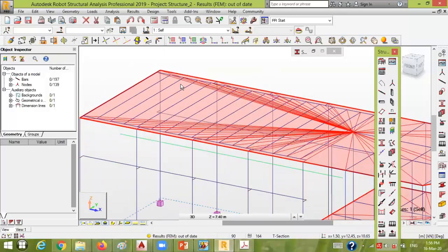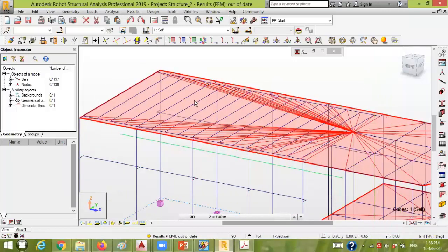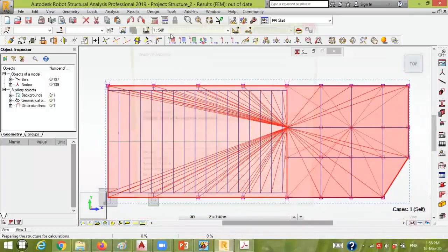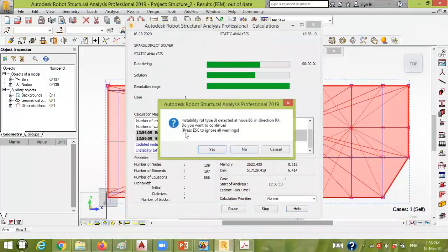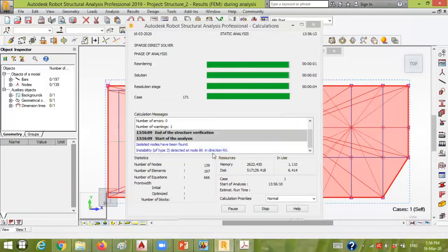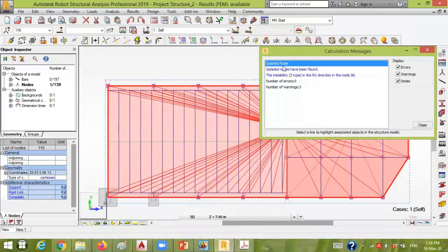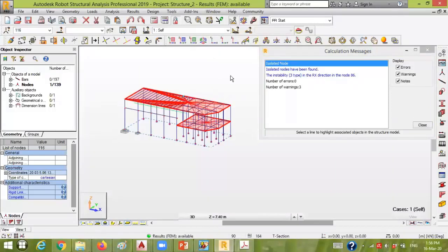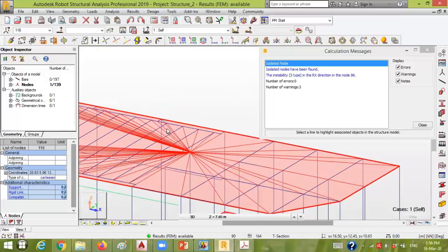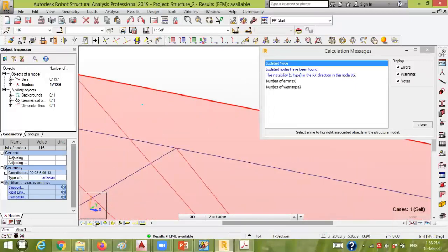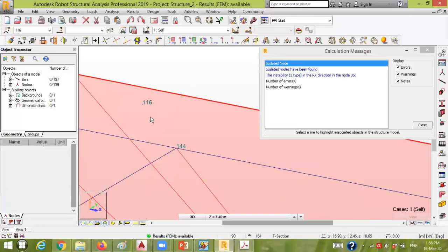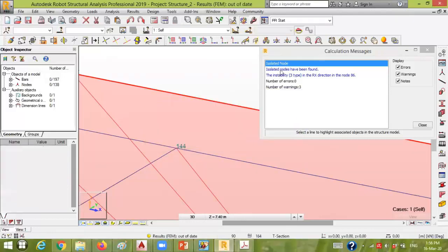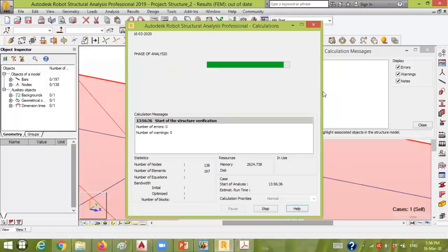So taking, for example, a view, deep view XY, you have to run again the calculation. Isolated node. I have one isolated node. I didn't delete. So isolated node here. I have a node alone. I must take and delete. Repeat the calculation again.